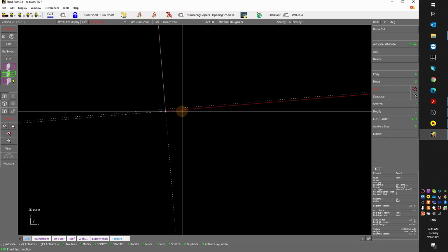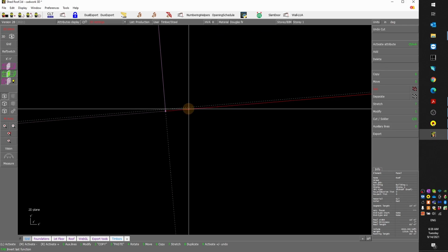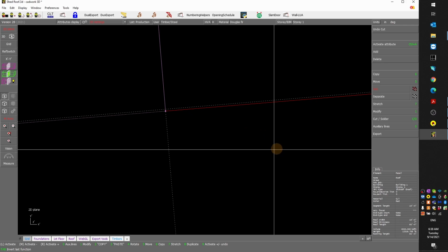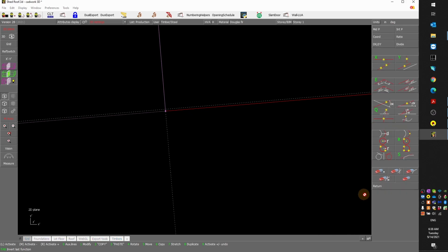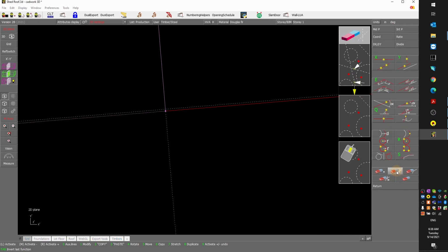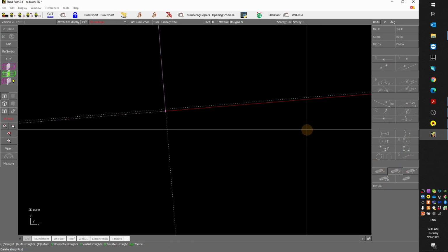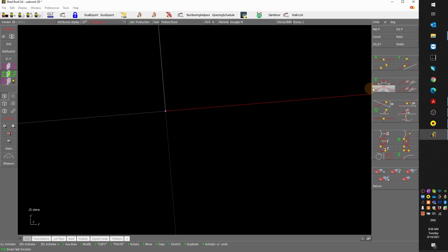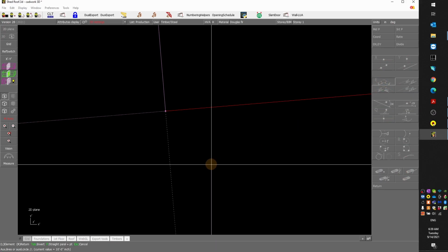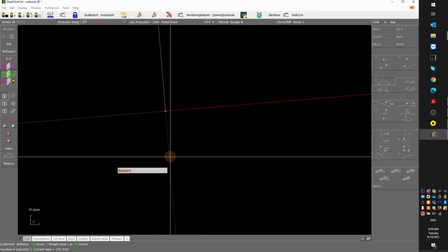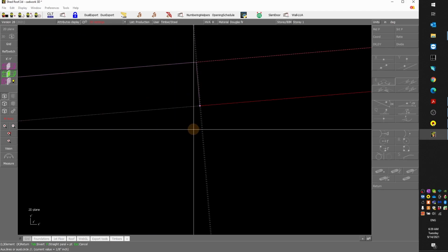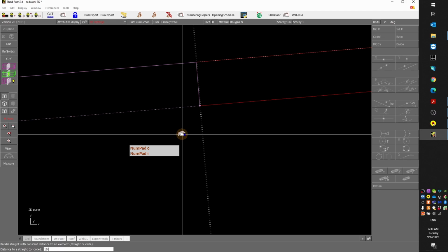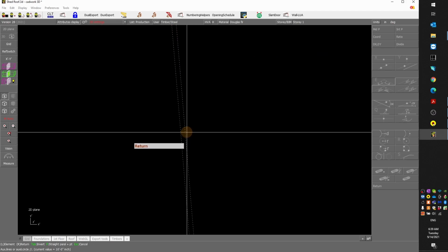Here, by mistake, I clicked slightly above the bottom of the panel. I can delete a line. So I go to the auxiliary line, left click on the line, it disappears, and I can continue with my offset 1/8 of an inch here, and 10 feet once more.